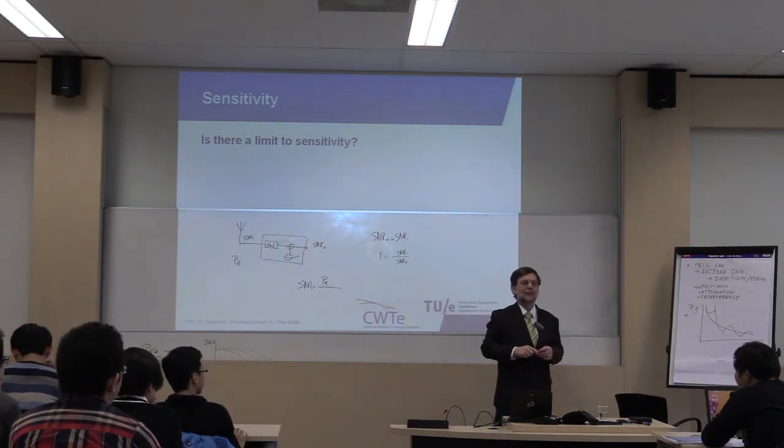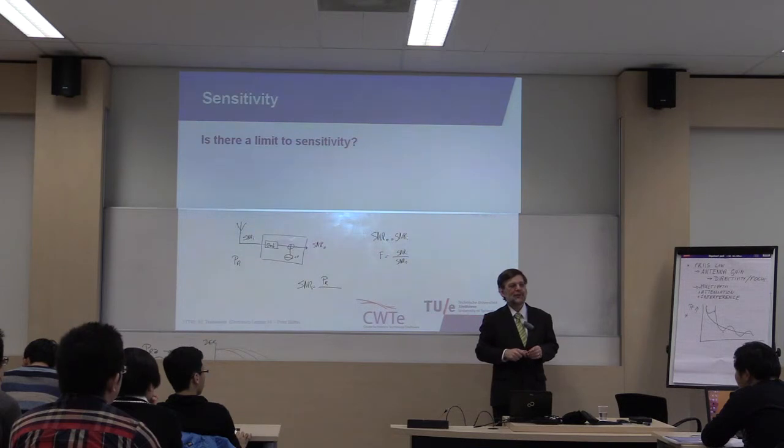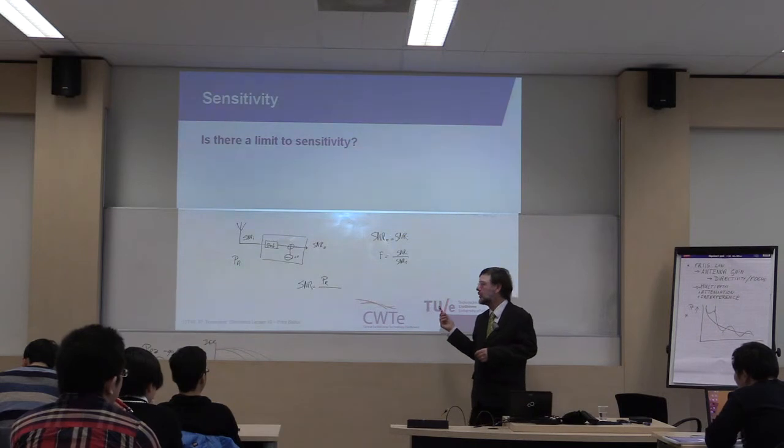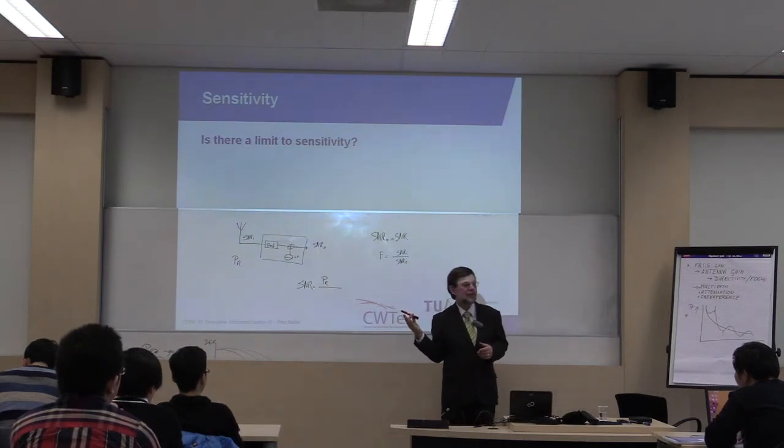Shot noise is not inevitable. Thermal noise is inevitable, but shot noise is something that you add yourself by doing non-ideal design. No, sorry, there's two kinds of noise. You mean flicker noise, 1 over f noise. But for RF systems it will not matter. For the frequencies we are talking about, you only have thermal noise basically.